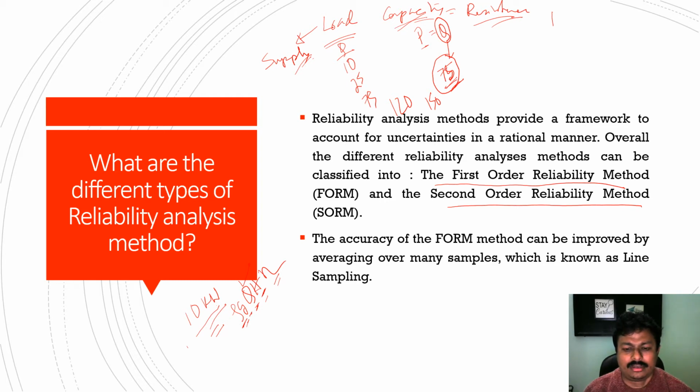So what we'll do is, we'll rank this discharge in descending order, where the maximum discharge will have the best rank. That means this 150 will have the best rank, followed by 120, then this, then this, then this. That means this will be awarded the first rank, second rank, third rank, fourth rank, fifth rank. Then it will be like this: this is 10, this is 25, this is 75, this is 120, this is 150. Okay.